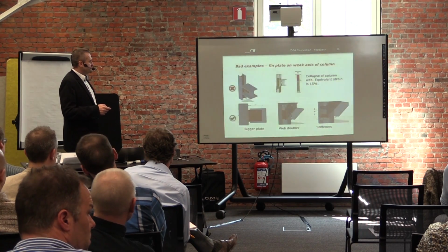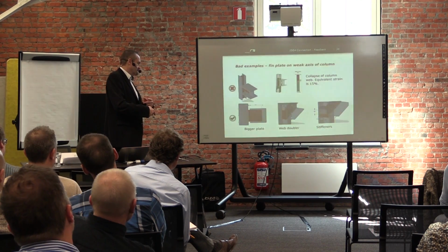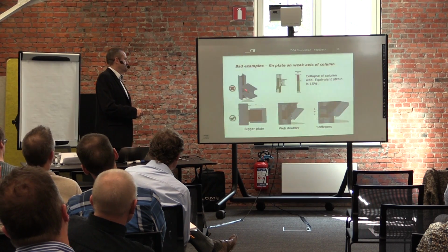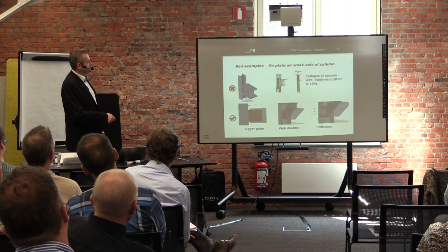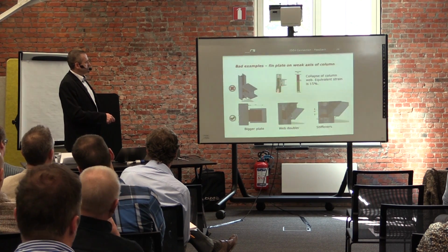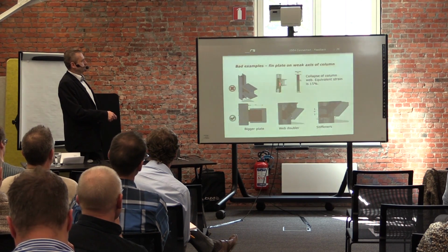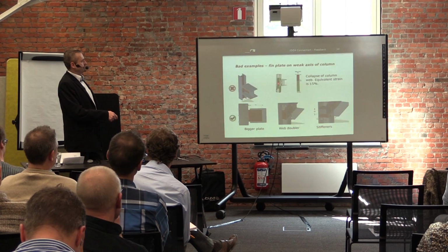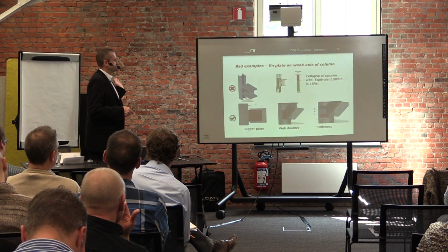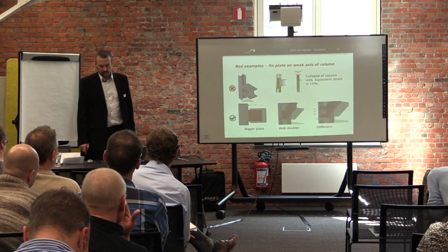This was the original design from one engineer, and another engineer who had to continue on the project said, I do not believe that it is okay. So we checked it with the CBFEM method, and you see here that there is plastification in the wall of this column, and in fact the wall collapsed because of this. And the strain was quite high.